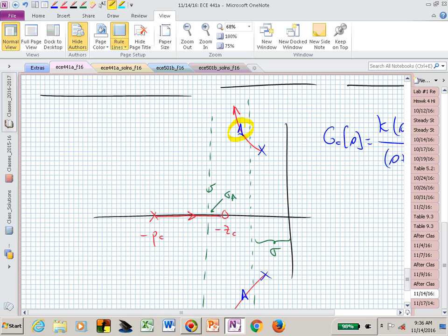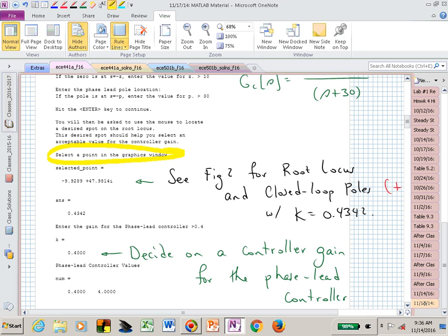Then MATLAB returns a number that actually says, oh, you've now picked closed loop poles at -10 plus and minus j50. Not a great angle, is it? But it is quite far relative to -2. It's now -10. So we have improved our settling time.